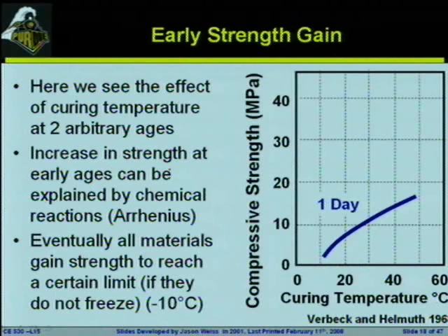Now, one of the things that we can start to point out, and I'm going to try to look at, is the strength developed at two separate ages. So here we have the compressive strength developed as a function of curing temperature at 1 day. And the basic idea here is simply chemical reactions are going to take place faster when the system is warmer. This is the same thing you saw in chemistry class.